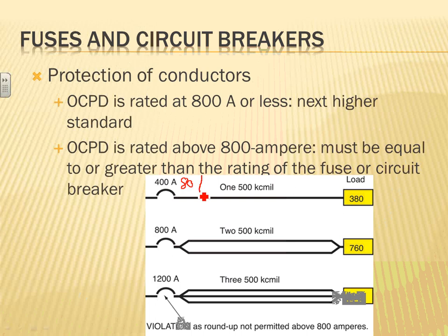If you've got an 800 amp breaker, if you put 800 amps on it and leave it there for the rest of the week, it's not going to trip. It's a code violation because the breaker will overheat, but it's still not going to trip. It'll hold 800. If you've got the high current curve, that breaker will hold 800 amps for a day.